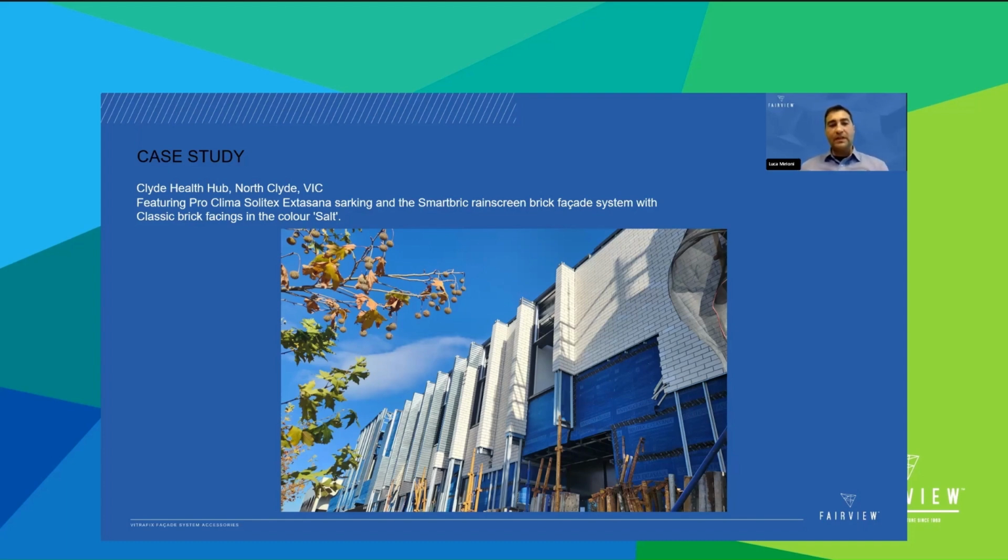Another question is what is the benefit from the G2 engineered aluminum? So the benefit overall is you have a lighter system, a tested lighter system. This could be a great advantage when you have, for example, a remedial project. Sometimes you have to remove a combustible cladding, which is made of lightweight panels with a combustible core. So if weight is one of the requirements for the project, and you are keen to remove only the panels, you can replace lightweight combustible panels with the lightweight non-combustible option. G2 is the right answer.